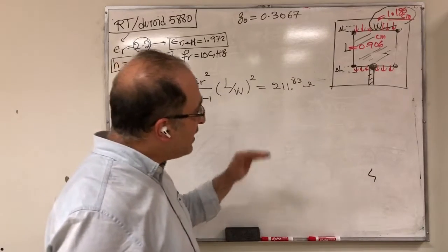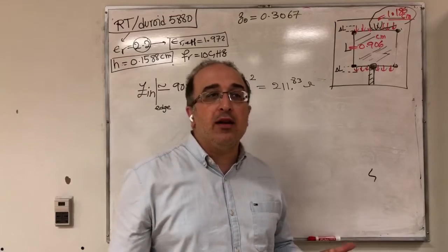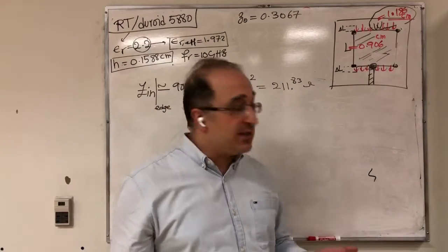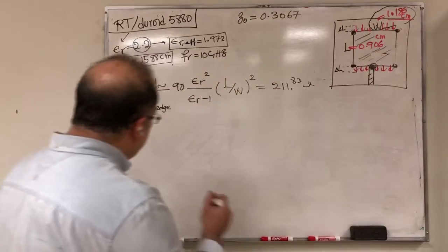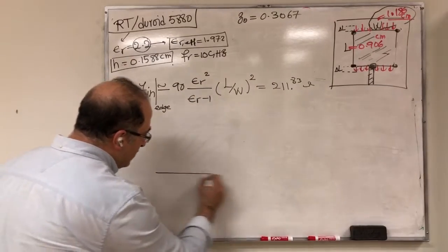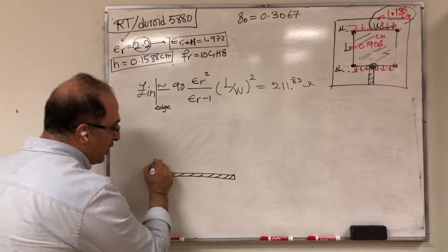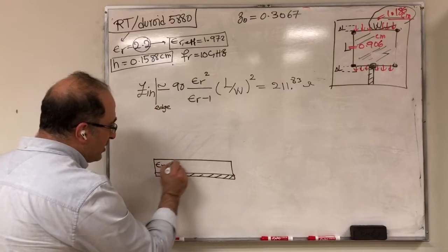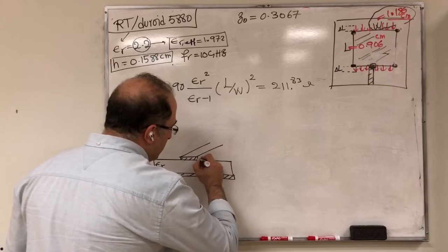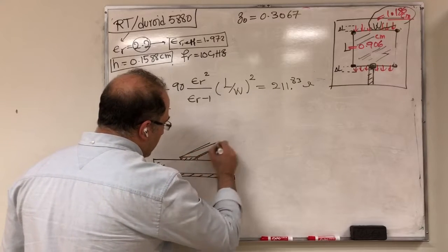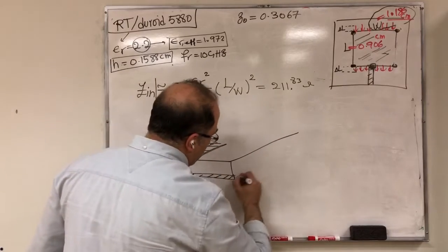Now, having that in mind, let's go back and revisit the transmission line model from the previous lecture. Let me again draw a three-dimensional figure of our antenna. This is my PEC ground plane, this is my substrate, this is my transmission line. Forget about this thickness for now.